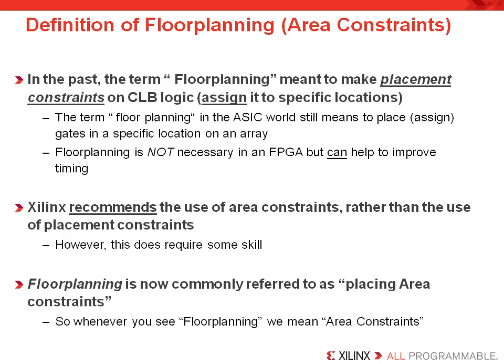Gate level floor planning is very difficult and time consuming. In FPGAs, floor planning improves timing by reducing routing delay without changing the gates in the design. But in fact, there are situations where certain timing problems are better solved by resynthesizing the netlist. As a general rule, engineers should floor plan hierarchy and not gates. Hierarchical floor planning is much easier as it serves as a guide to place and route of your logic.